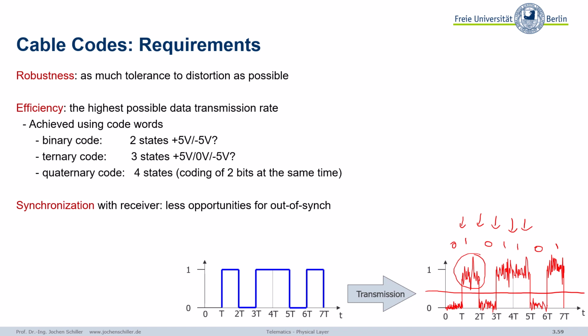Inside your computer, this is very simple. Because inside your computer, if you have a computer chip, you always have a clock line, and this clock line is distributed all over your chip, and so all components know exactly when is the rising edge of your clock and when is the falling edge of the clock. So you have a clock distribution tree or several of them. Yeah, it's also complicated, but that's basically how it works. So the components know this, and then they know exactly when to sample. So flip-flops, when to sample the signal.